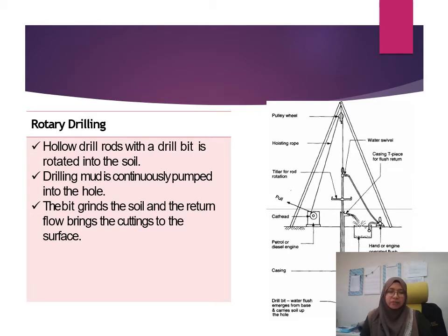Okay, so the flow of the water with the drilling mud will return to the surface. Okay, and then from that we can collect the soil sample. Alright, so for rotary drilling we have various size of the equipment. So the bigger the size means that the deeper the borehole that you can advance.